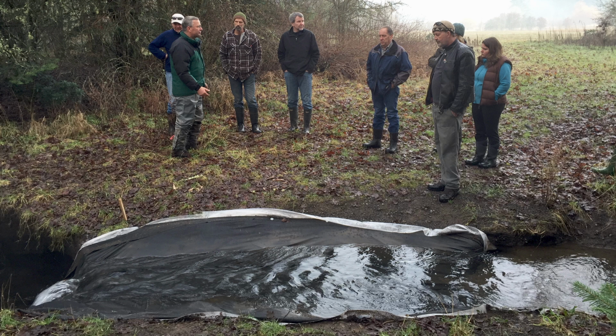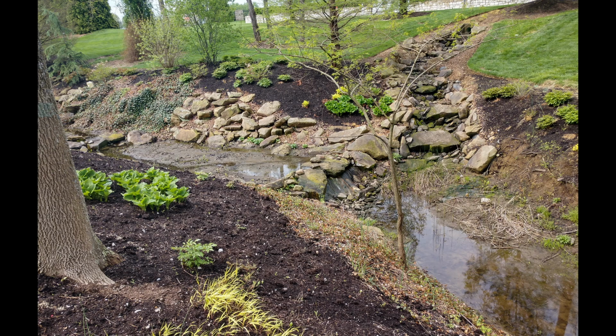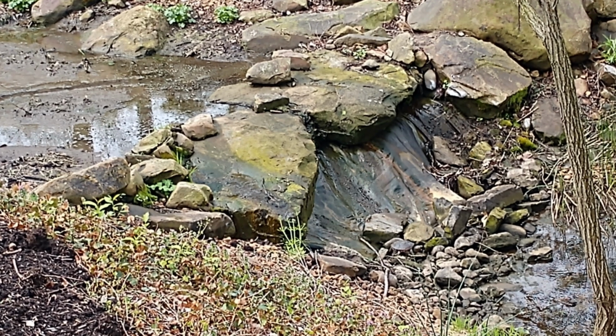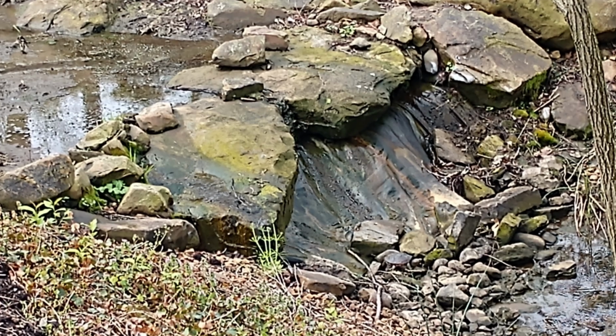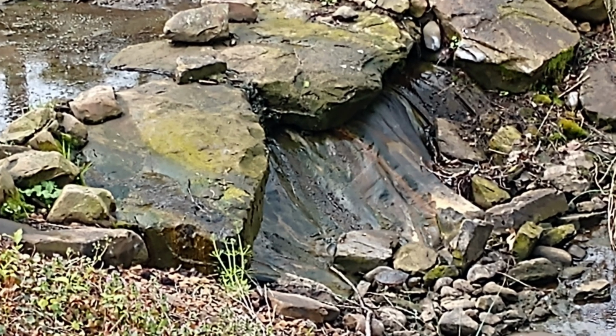The permanent solution is to restore the streams and wetlands and then to install buried vertical grade control structures across the floodplain of the stream where head cuts are located. Here's where someone used plastic to armor the base of a riffle and vertical grade control structure in a ditch they tried to make look like a stream in northern Kentucky. The pool doesn't hold water and the rock and gravel they placed in the plastic has washed downstream.